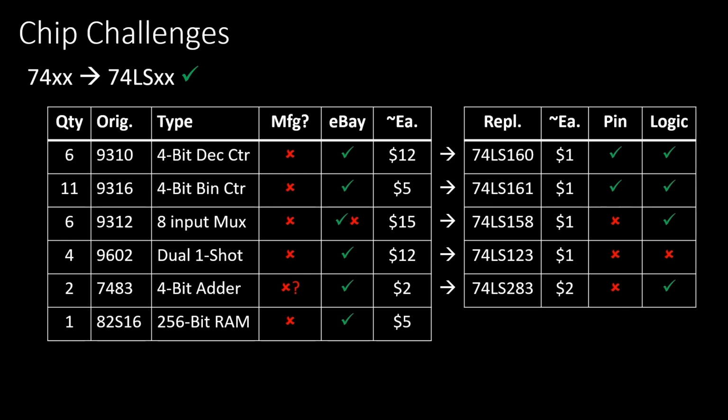Not made anymore, but nothing we can do but buy them off the interweb. And fortunately, a lot of companies made these compatible parts, so I'll drop a list in the docs. You can also use open collector versions of these chips. For example, we could use the 82S17 with a pull-up resistor on data out. And you see many boards with pull-up resistors soldered from data out to VCC, so I'm assuming these are all open collector versions. I think we've had enough fun for now. In the next part, we'll trace out the Rev F board and update the schematics.